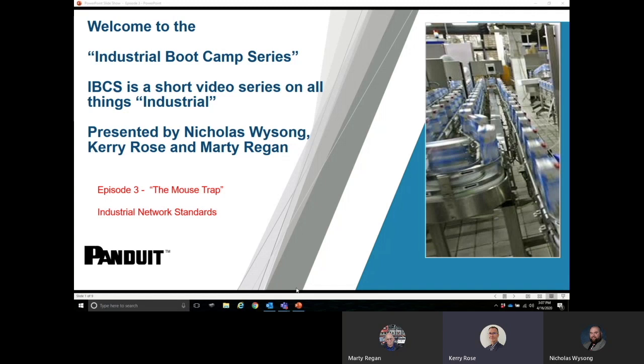In our last episode, we examined TIA 568 and TIA 1005 industrial standards and how a standards-based approach to cabling infrastructure will improve our performance, scalability, repeatability, and operational maintenance within that network. We highlighted and contrasted the variations in TIA 1005 versus TIA 568, including the hardening of equipment, pathways, the six connector channel, and edge connector variations. One of the components of the TIA 1005A standard is the classification of industrial areas using what we call M.I.C.E. Next slide.